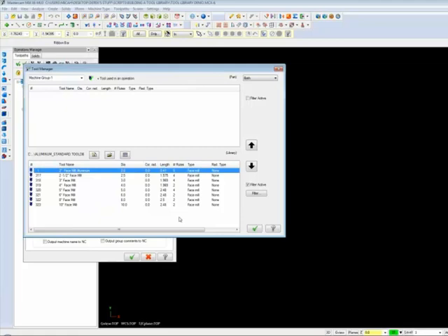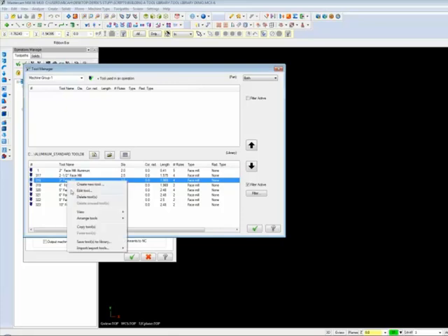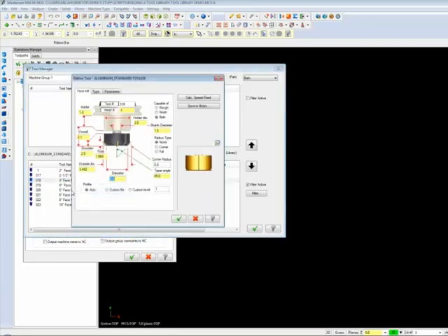The next tool we'll program is the 3-inch face mill. Select the 3-inch face mill, right-click on it, and select Edit Tool. This tool will be tool number 2. The carbide inserts are the same as the other face mill, so we'll enter 410 thousandths for the flute length.